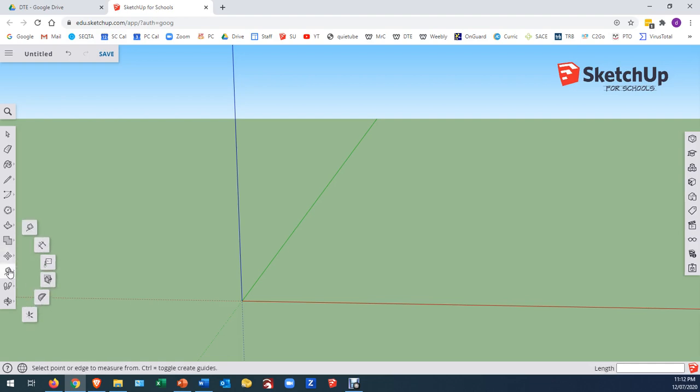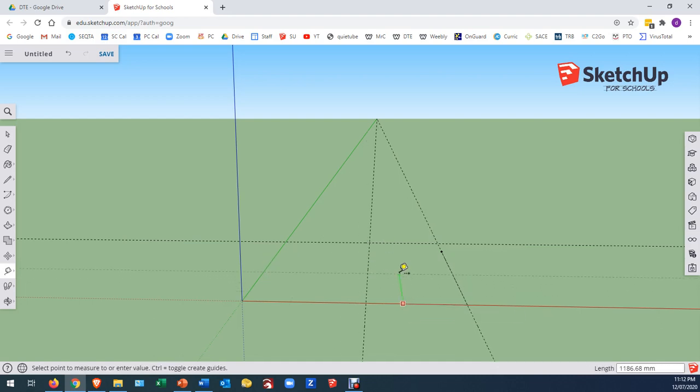Over here we have a variety of tools that are around measurement. This one is a tape measure. It allows you to measure distances between 2 points, or to put out what are called guidelines, or in some cases to put a guide point. And you would normally do them at a fixed distance, and we'd be typing that. But this is a very useful method of doing this, because sometimes laying down a grid of points will allow you to then join lines in between these grid points as you need. Alright, a very, very useful tool, and one that I hope you get to learn, or hope you use a lot of. I certainly do.